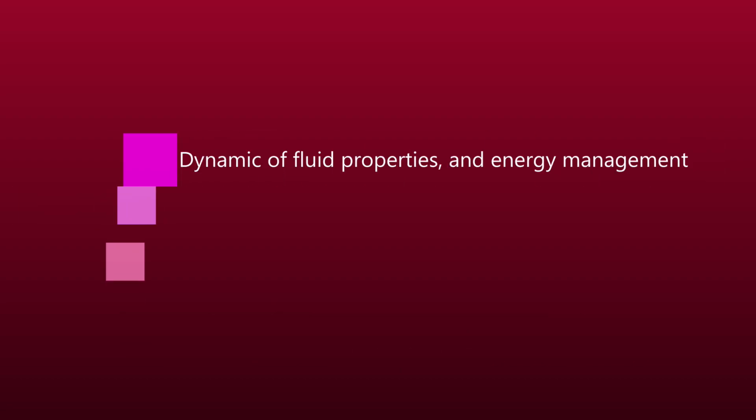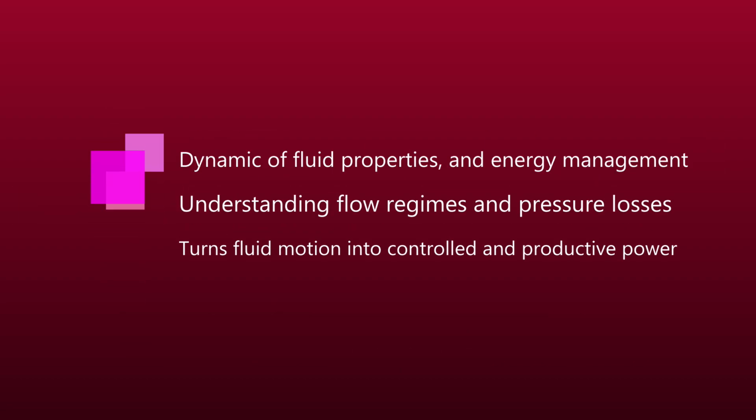In conclusion, hydraulics is a dynamic interplay of pressure, flow behavior, fluid properties, and energy management. From understanding flow regimes and pressure losses to applying rheological models like the Bingham plastic, power law, and Herschel-Bulkley, each concept contributes to predicting and controlling fluid performance. When these principles are applied effectively, engineers can optimize bit hydraulics, maximize mud carrying capacity, and design systems that are efficient, safe, and economically sound.